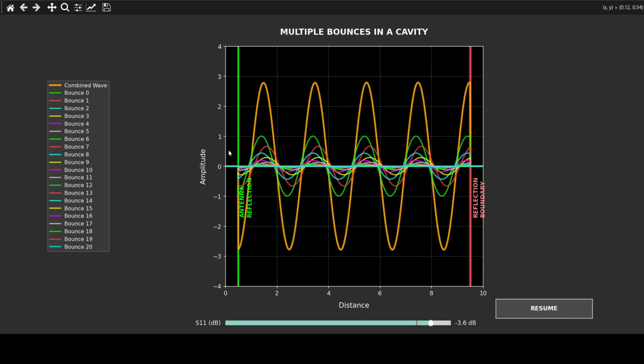And this is problematic, especially in modulations where the frequency difference between each channel is very small. So whatever distortion you add here, it can transmit back to the air and cause issues to the neighbor channels. So that's one of the things I talked about: the distortion.